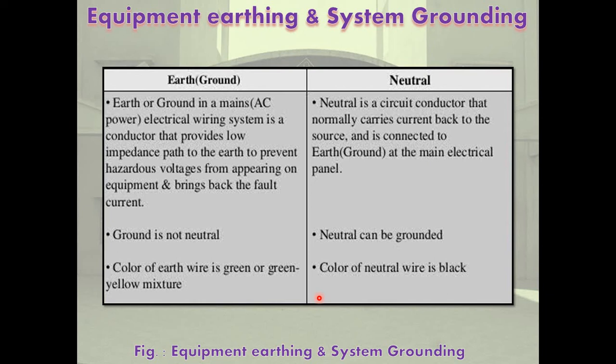Equipment earthing is connecting the non-current carrying metallic parts of electrical machines and equipment to the earth. Equipment earthing provides safety to personnel against severe shock from faulty electrical machines or equipment. Earthed metallic parts remain at near earth potential and therefore the earthing provides safety. Touch potential and step potential are within specified limits. Earth fault protection of equipment becomes easy because leakage currents flow through the earthing connections.